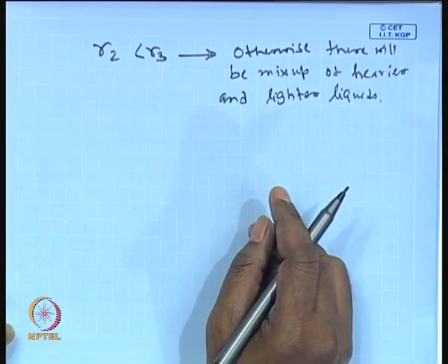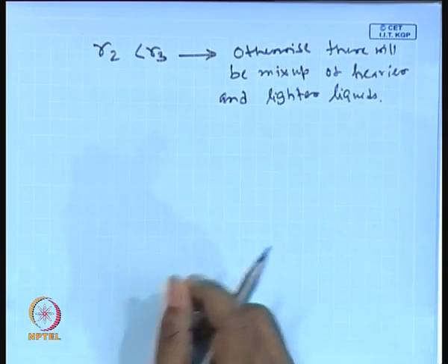Okay. So, that is the basic principles of any centrifuge separation process, and we have discussed the principles for the slurry, that is the solid liquid system, and the liquid liquid systems, and various scale up issues as well. So, the idea is if you know in the laboratory scale that given a centrifuge, its dimension etc., and all operating conditions given, this is the extent of separation you are going to do. Then if you would like to scale up, you can do appropriately. Okay. So, once after doing this, let us look into some of the examples, so that the calculation procedures etc., will be clear to us.